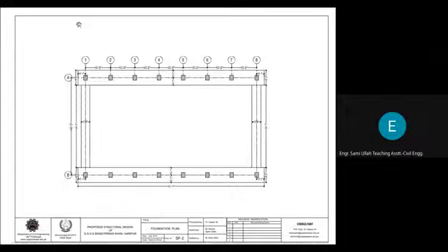Reinforcement is provided in this manner. This is the column reinforcement. Here we have provided 12 number 6 bars. The plain beam has been provided. These are the beams now, provided in this manner. You can see the beam with skin reinforcement, and you can also see the positive reinforcement here.